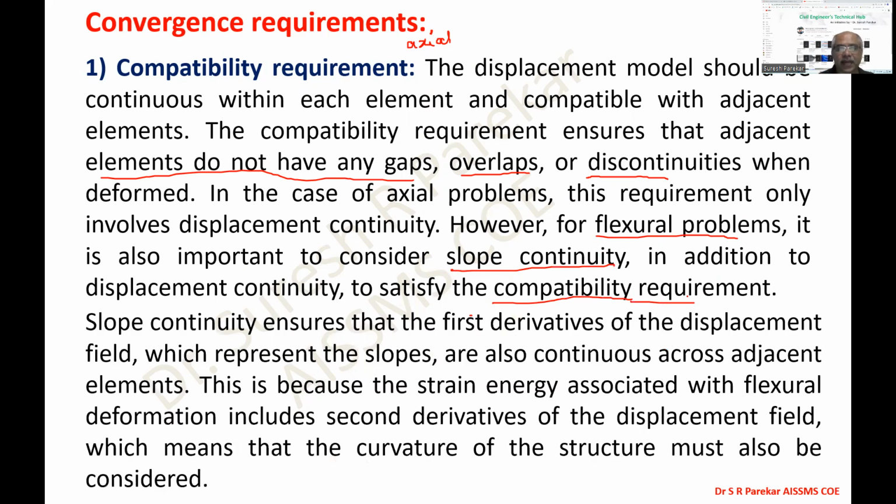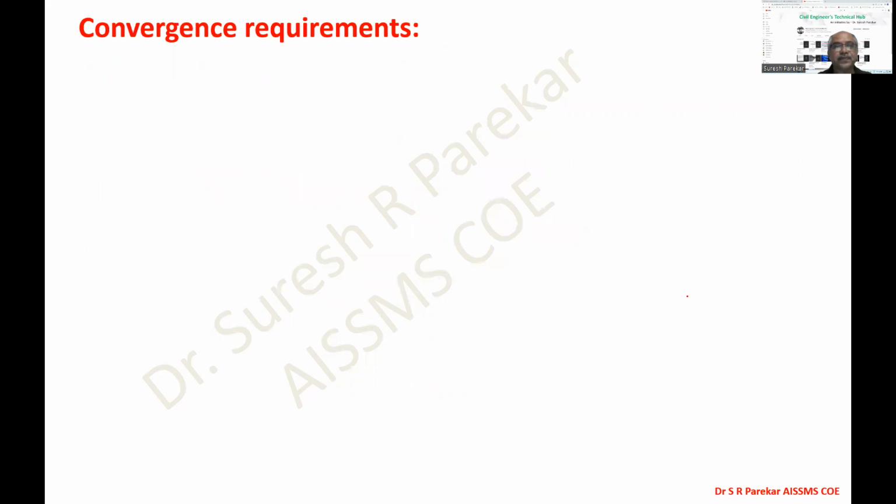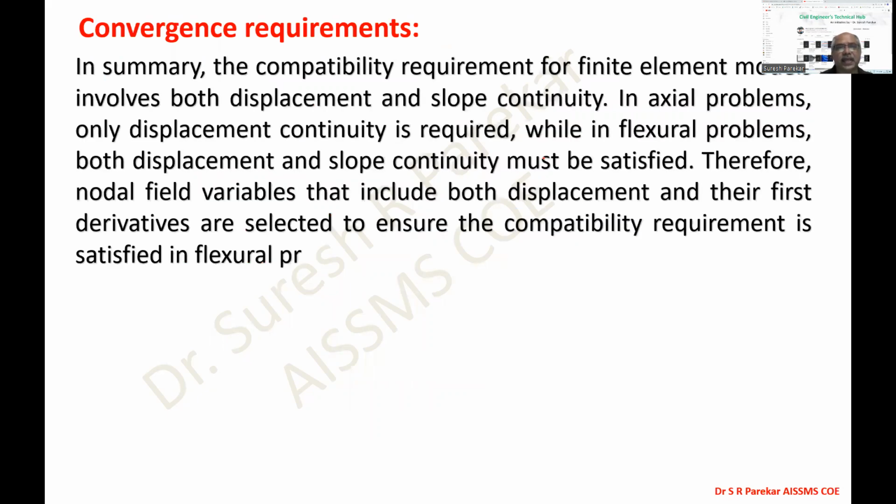So compatibility requirement simply means we have to ensure the continuity of the displacements. In summary, it is clearly mentioned that the compatibility requirement for a finite element model involves both displacement and slope continuity. In axial problems, only displacement, while in flexural problems, both the displacement and slope continuity. And considering this, we have to consider this displacement model so that we ensure the compatibility requirement.